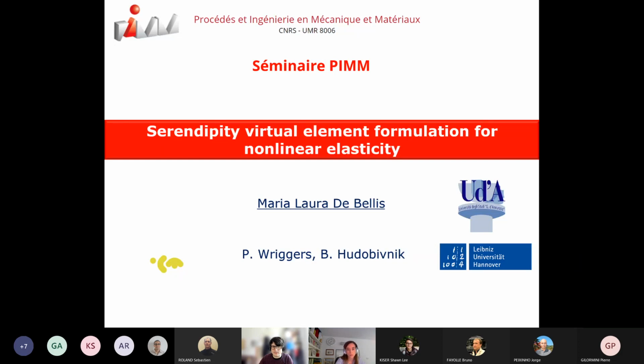I take this opportunity to share with you some results of recent and ongoing collaboration with Professor Wriggers and his co-worker Blaž Udobivnik from the Institute of Continuum Mechanics in Hannover at Leibniz Universität. The focus is on the virtual element method, in particular the serendipity virtual element formulation to model finite strain problems involving compressible and incompressible materials.